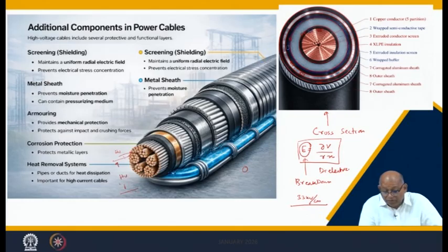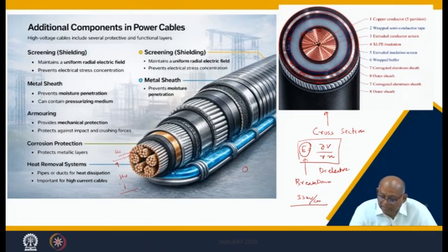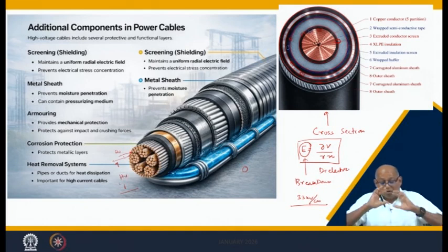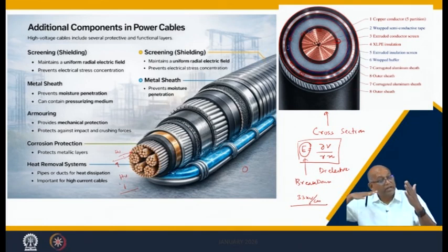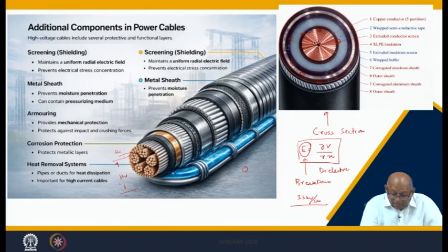The screening is responsible. You can see one copper screening here. There is aluminum clad, and these are steel, for the armored steel. You can see here the copper conductor. Then this is the screen, the third layer, layer 3. So layer 3 is the copper screen. The screen is responsible for terminating the electric field. Electric field going onto the metal becomes 0, becomes parallel, and reflects back. It cannot penetrate a metal, it will short circuit. So this is called a conducting screen.